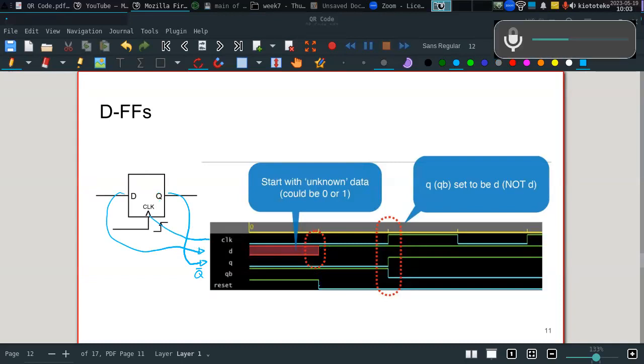So you can see here, you put down the reset, and that's when you start playing with the inputs, no? You can see here that the D input is 1, the Q is 0, and the not Q is 1, and the clock is 0. So again, the flip-flops only work when you have a rising edge. So whatever you have in the rising edge,